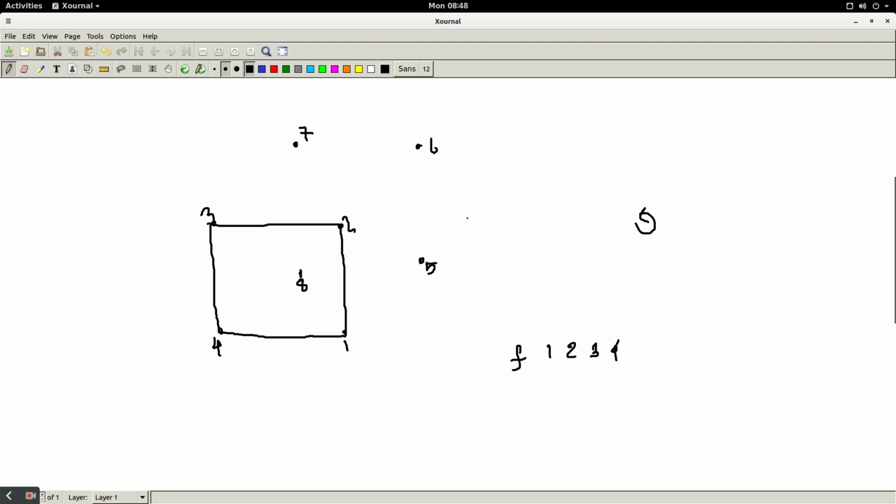You see over here 1, 2, 3, 4. This one makes sense because you're going counterclockwise. 1, 2, 3, 4. If you go 5, 6, 7, and 8, that's going to be wrong because that's going to be the internal face inside the cube, but you want it to be on the outside.